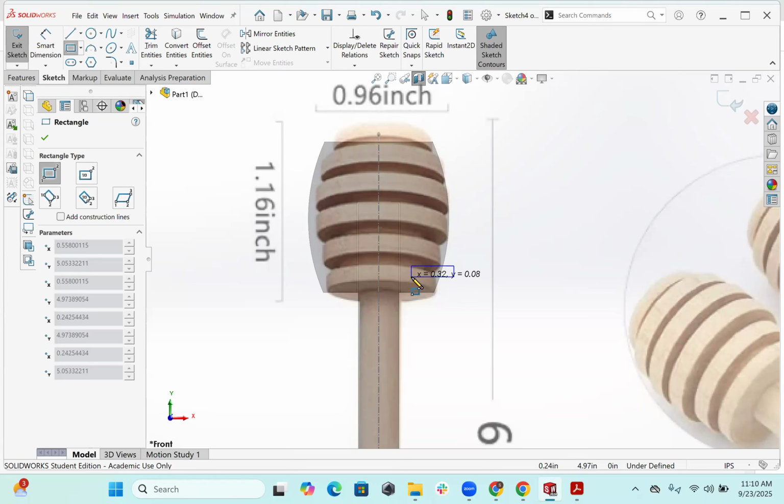Everything is black. So now that we have one, rather than building each of these, because everything looks the same thickness, we're going to pattern this upward. So if you look for linear pattern, you can select that. Linear pattern stands for patterning in a line format. Basically, x-axis is one line, which goes flat, right to left, and y-axis goes vertically. So right now it's giving us x-axis and number of patterning is 2. We don't want that, so I'm going to go back to 1 here.